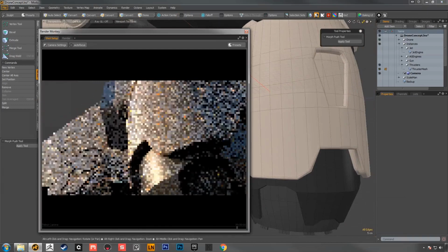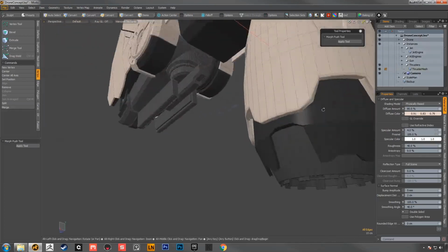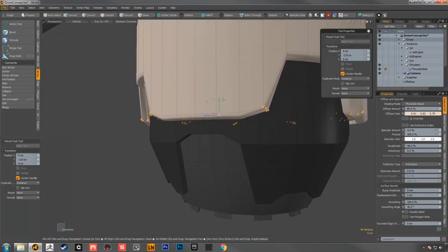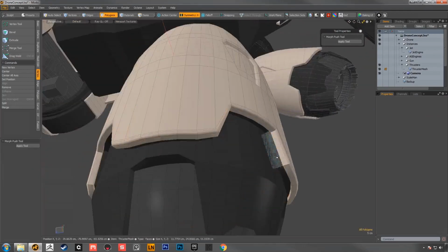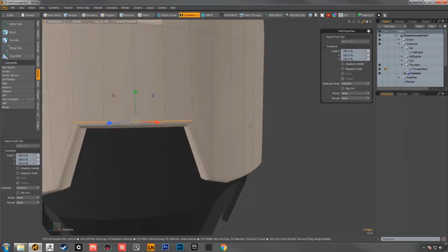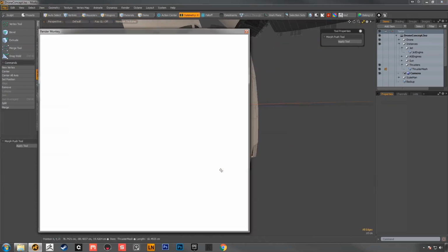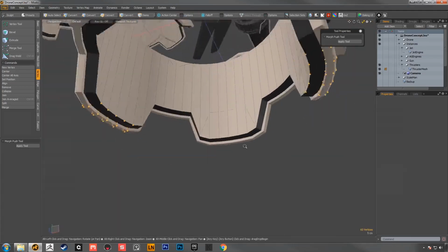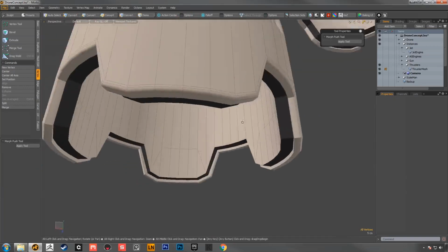And I'm doing the same here. I'm just adding that small bevel, forcing the normals, seeing how it looks in the render. Because in the render already you can see that those bevels look like they could quite easily be a turbo smoothed part of the asset, or like a 3-sided bevel as opposed to a 1-sided bevel. And then in UE4 it will look pretty believable. It will look pretty close to a high poly asset. So this is the slow process of going through and adding these bevels and experimenting with them. It's a slower process on a piece like this because it is curved.